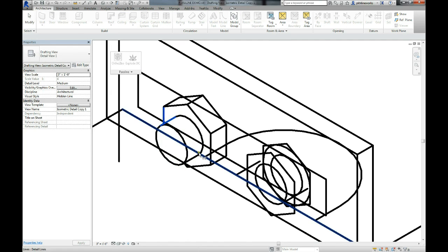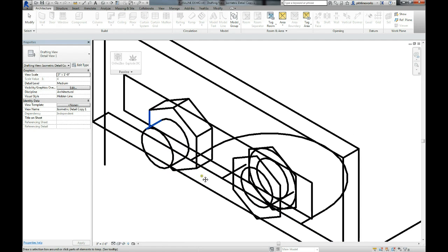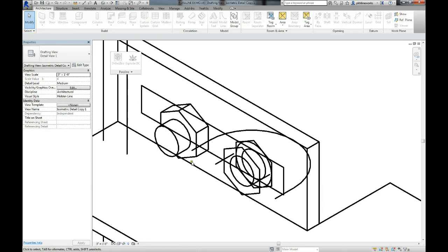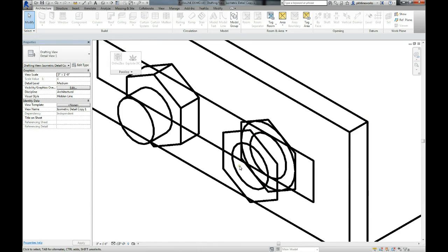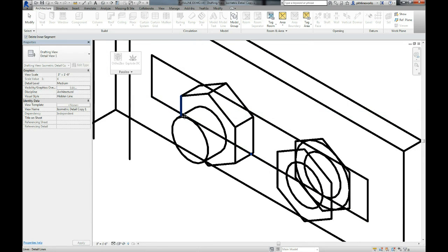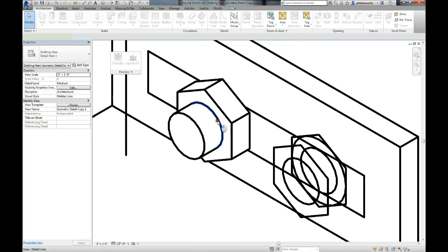Start peeling things back so that, yeah, you can see it's beginning to take shape. This of course wouldn't be seen here. This won't be seen, so I'll just get rid of this for now. If it wants to slice to the right line, just tab and it'll slice the intersection point of the two lines. Very handy little tool they've added in for Revit. And there you go.